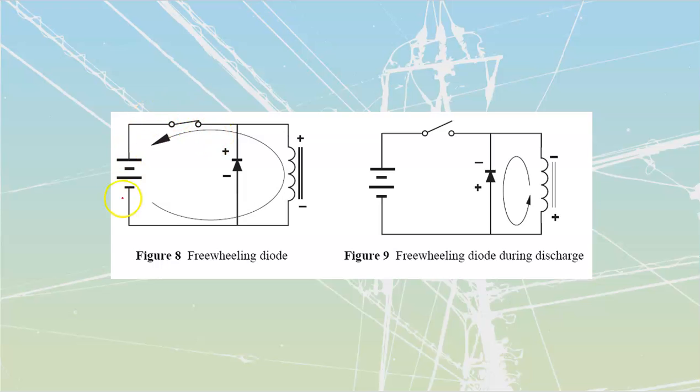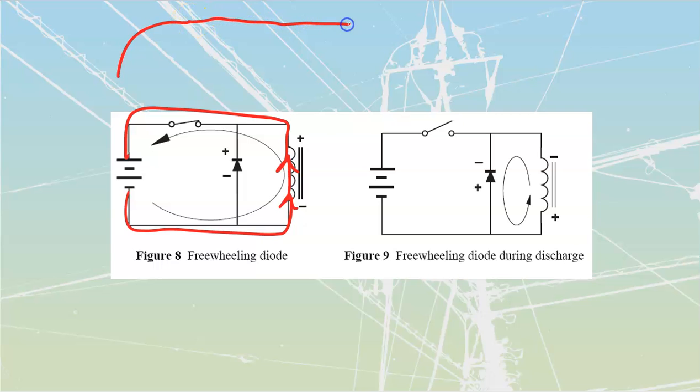When I close this circuit, I'm going to have current traveling through this inductor in this direction. My inductor doesn't like it when the switch is closed. When the switch closes, it's going to slope in that current, but then the current's going to hit steady state. And when it's hit steady state, the inductor is going to be fine. It's just going to be dealing with it. It has its lines of flux stretched around the outside like this.